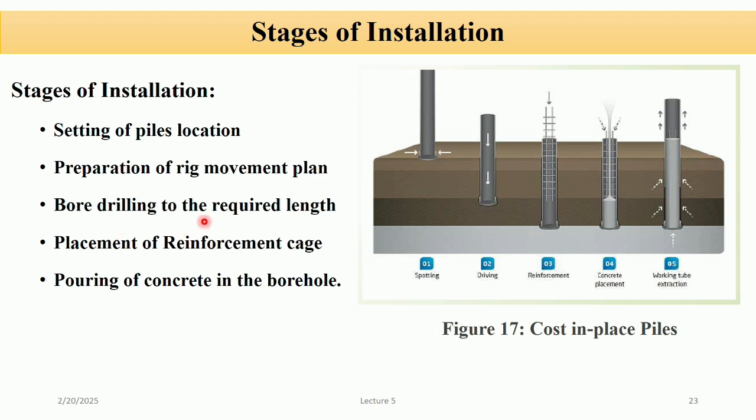Bore drilling to the required depth. Use specialized equipment to drill a hole at each marked location, reaching the necessary depth as per design requirement. Placement of reinforcement cage. Carefully lower the assembled cage into the drilled borehole, ensuring it is correctly positioned and secure.